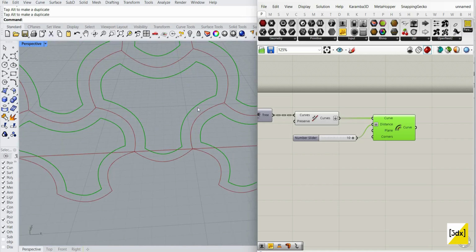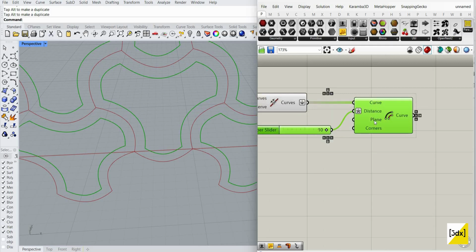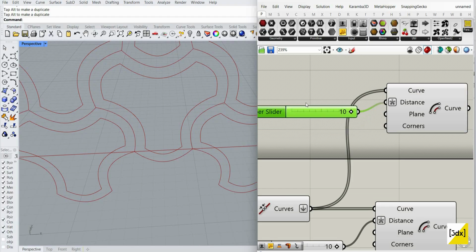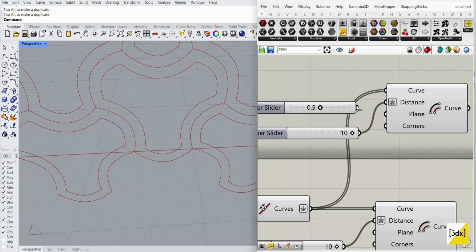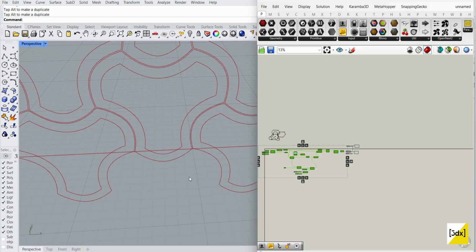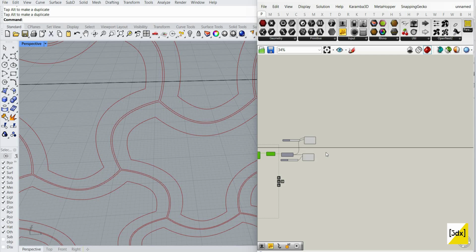Now, if I'm creating a surface from the joining, it doesn't make sense because nothing will be this accurate, so I give a tolerance. I'll just do Ctrl-C and Ctrl-V. Obviously it takes some time. My computer is very old. Maybe I need to change it in the future. I'll give it a 0.5. So it creates a tolerance. Now I'll just hide these two things. So you can see it creates a tolerance. There are multiple ways to create a surface like this.